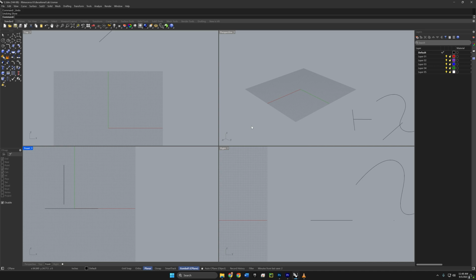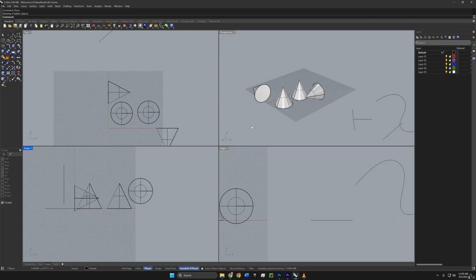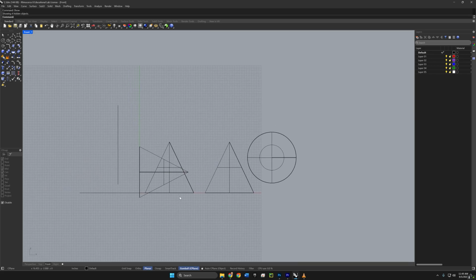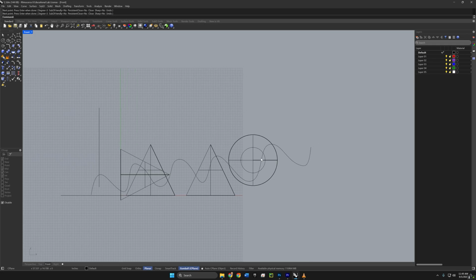Now we'll take a look at the project command, which is also viewport dependent. So we'll bring the cones back by typing show. And let's go into the front viewport. I'll maximize it. And I'm going to create a control point curve and make it squiggly in a way that overlaps these cones. Okay, and now we'll run project.